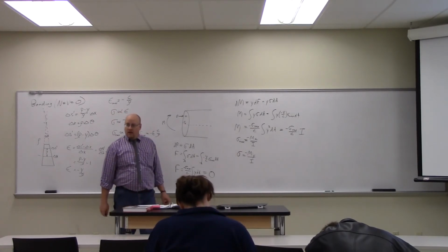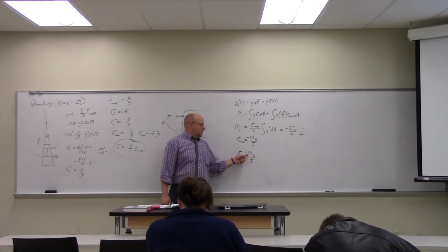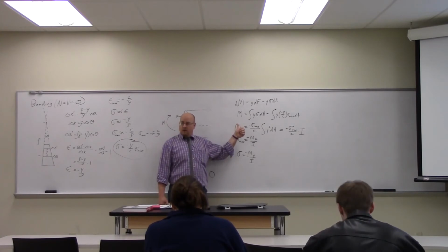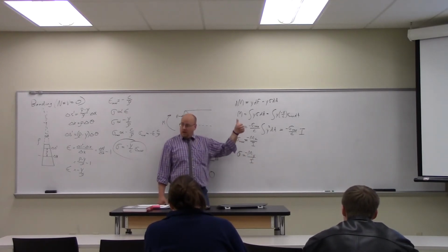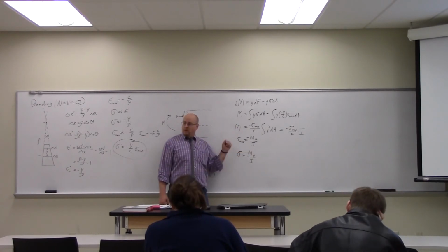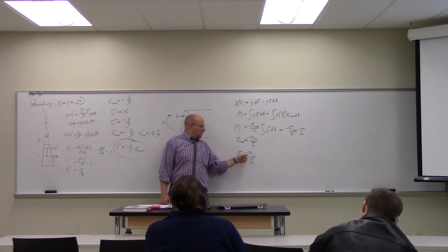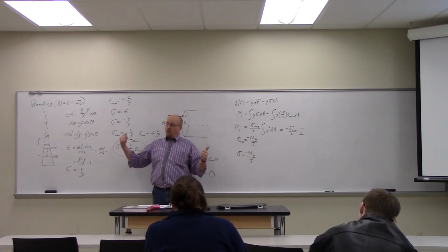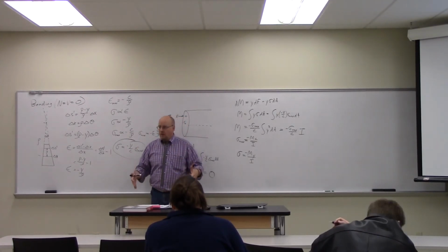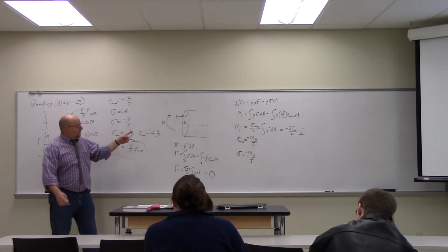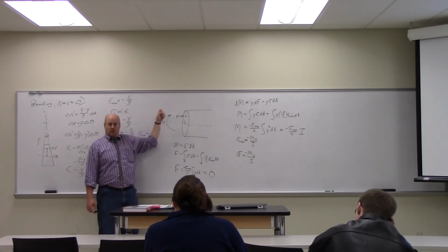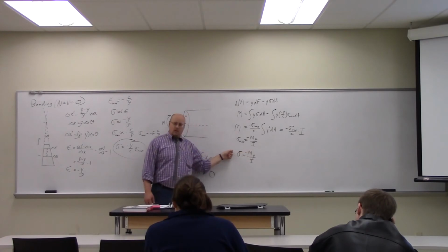So what does that tell me? That tells me that as I leave the neutral axis, as I move away from the center, my stress increases with distance linearly and depends on the ratio of the applied moment to the moment of inertia. And it's negative. As I go up in y for a positive bend, I get a negative stress, therefore compression at the top and tension at the bottom. And the reason this is a positive M is because it's causing it to cup concave up, to hold water. So this positive M gives us a negative compression on top.